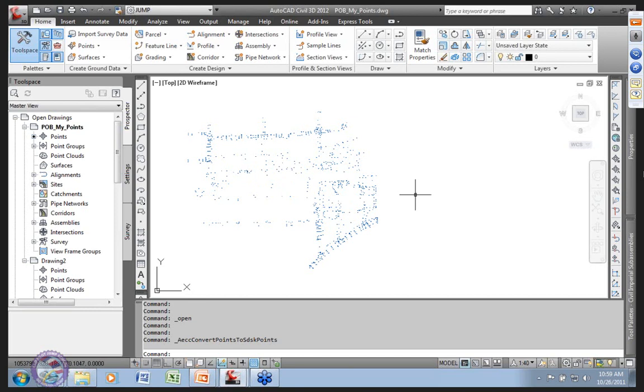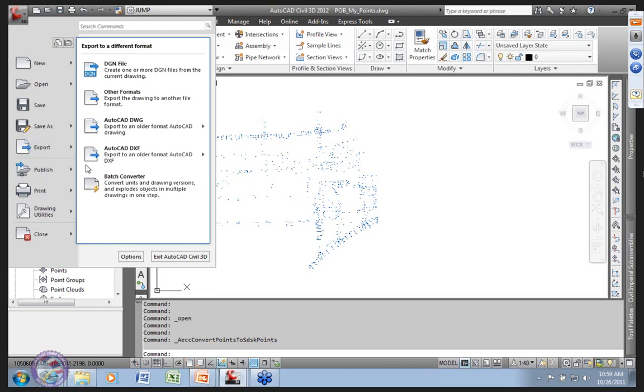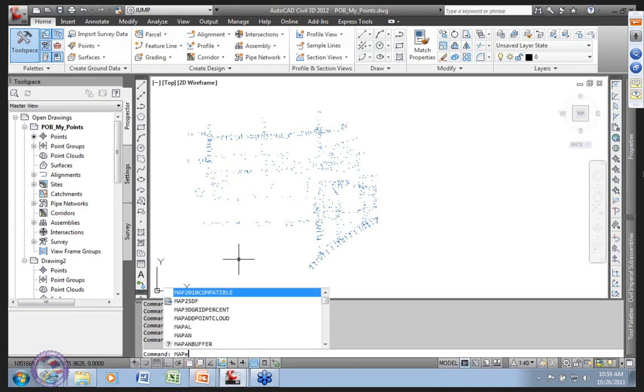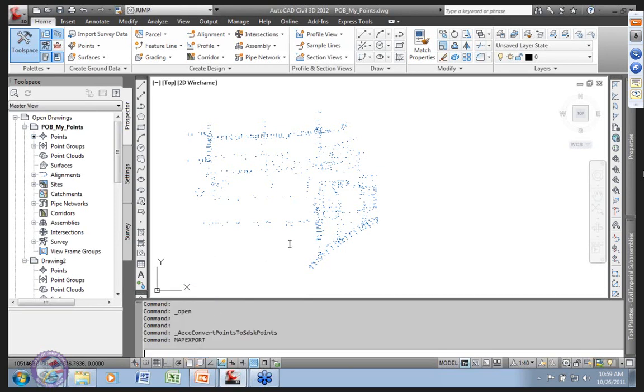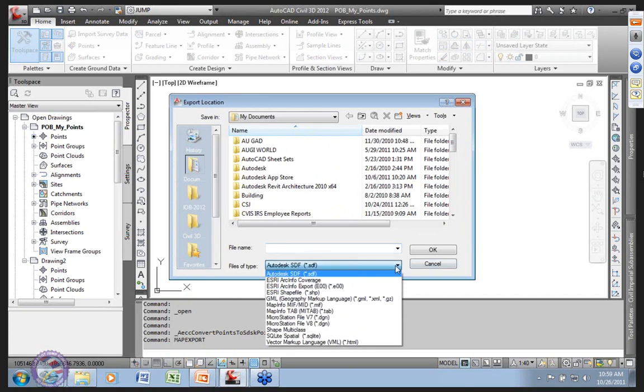Okay. You should also recognize that Export is actually really good at DGN files if you understand Map Export, right? And that is a better way to do this than this Export. So Map has Map Export, which since you're in Civil 3D you've got, and how would I find out what that command's called, right? MAPEXPORT. Okay, yeah, this is a little more elaborate. Okay, what do you want to do? Okay, I want